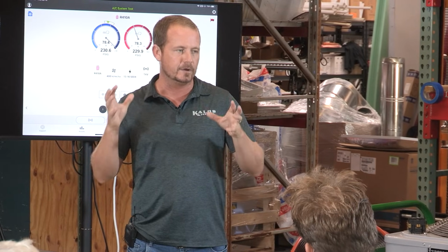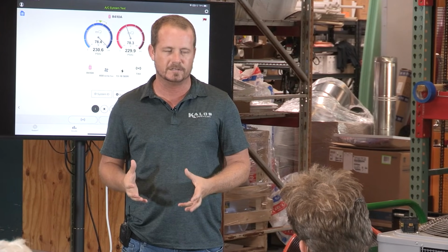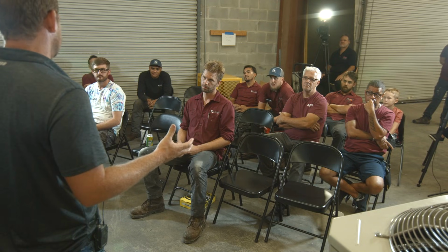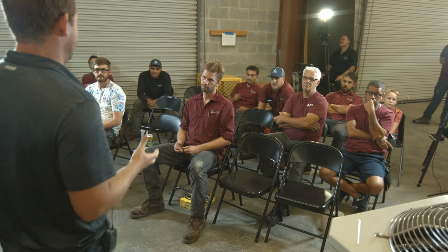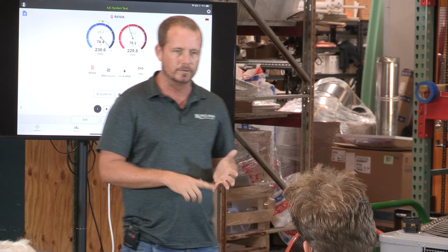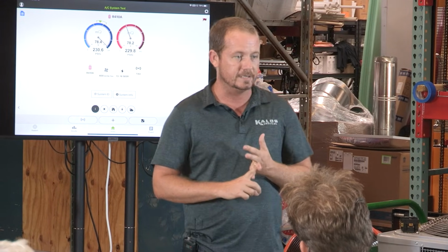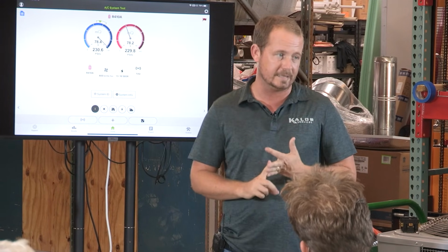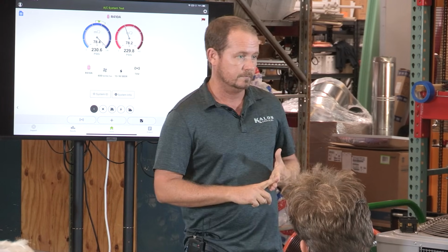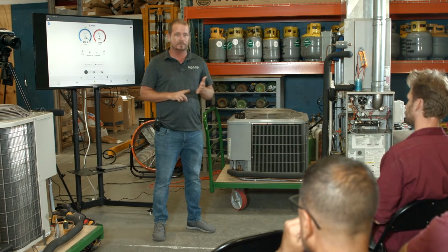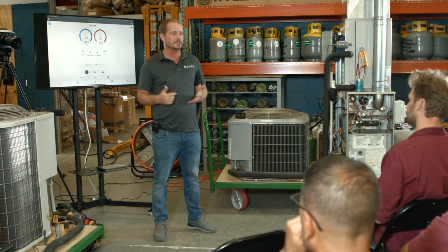What is the root problem that caused those symptoms? It's airflow, right? TXV metering device. Sorry, I didn't tell you what metering device it was. Because your superheat is normal to low, your suction pressure is definitely low, your delta T is definitely low, and your head pressure is a little low. Right? Those are all indications of poor indoor airflow. So those are your symptoms.